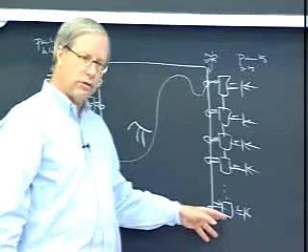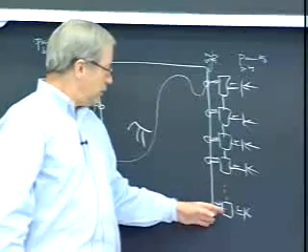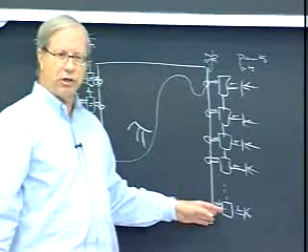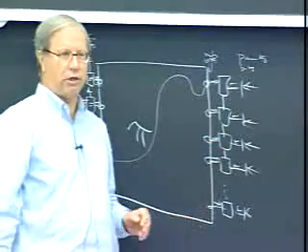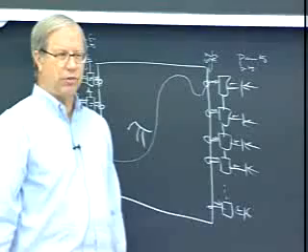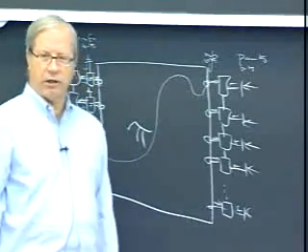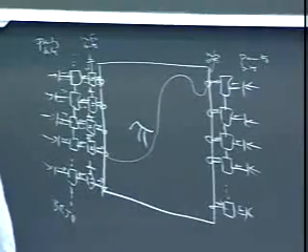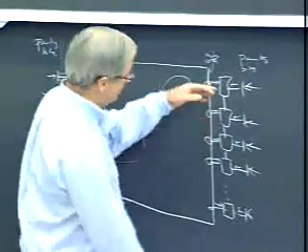If you think of it in signal-to-noise ratio terms, as some people do, you hopefully have improved the signal-to-noise ratio in the information that's coming over. It's as though you received these bits over a higher quality channel. They tell you more about the information bits than you got just from looking at the raw data from the channel. That's basically where turbo comes from.